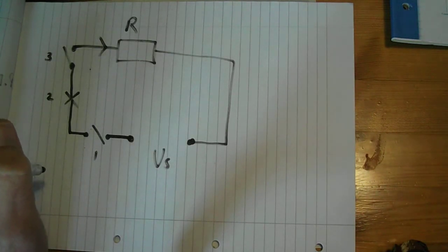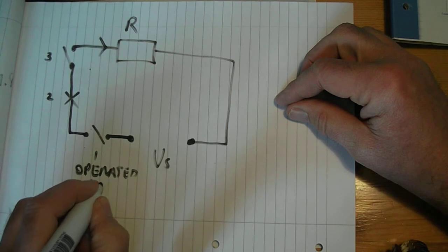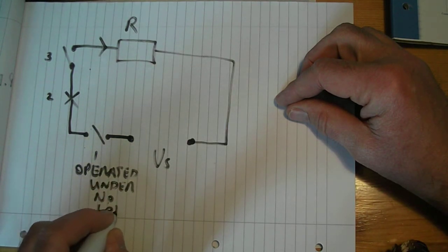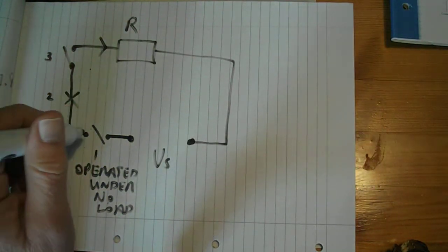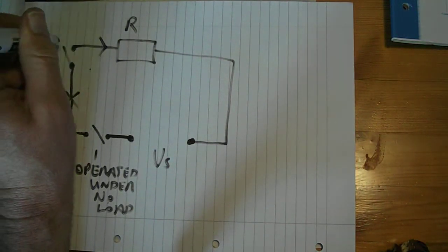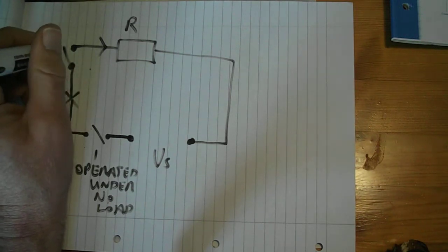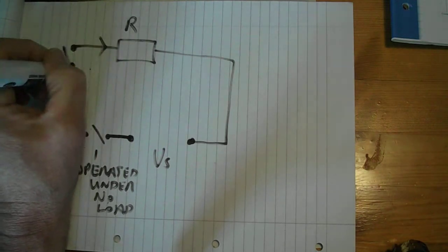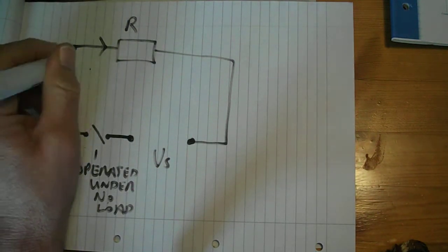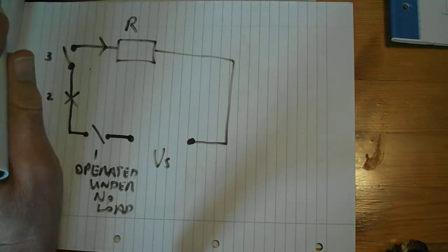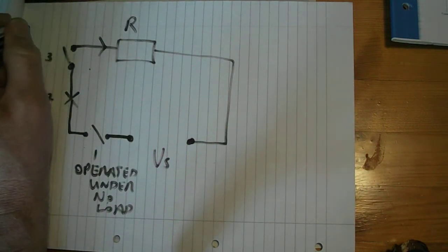Now an isolator is a form of mechanical switch, but it's designed to be operated under no load. That's very important. It has to be operated under no load, because these things are not really designed to control the circuit. The switch is designed to control the circuit, and the switch is very often an oil or a gas circuit breaker, which is designed to switch on and off at fairly regular intervals. Because when you switch on and off the circuit, you'll get a lot of arcing across the contacts, which will deteriorate the contacts. And in an isolator, if you use that to switch it on and off regularly, it would damage the isolator. So you only use a switch that's specifically designed for that. So that's a symbol for a switch.